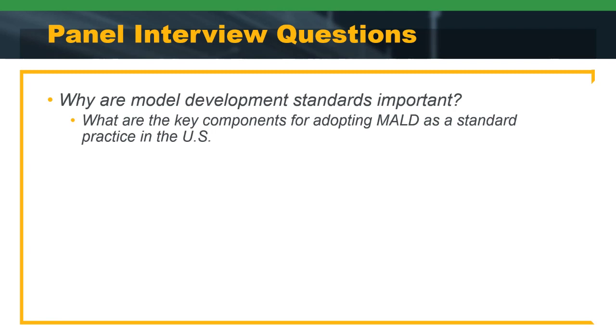So really, it starts with that model progression specification that you have to build on that level of development, right? So you can clearly communicate what you've done. And a lot of what we talk about nationally is focusing on the final turnover, but eventually you've got to break it down to those milestones at the contract level. But really just developing those fundamental communication tools so that the contractor knows how to work with it. And I think one of the things that makes us a little bit different in the infrastructure world is that surface and that location piece that you don't typically have to deal with as much in the building world. So how do we account for that in these definitions?